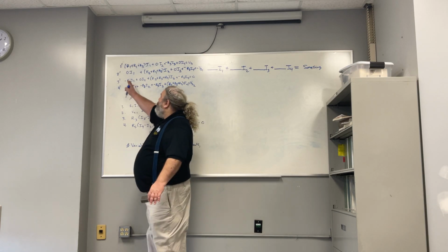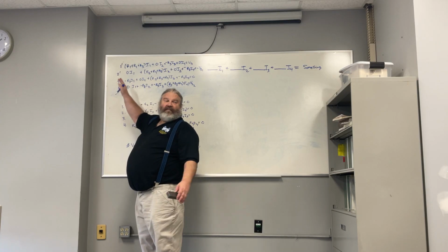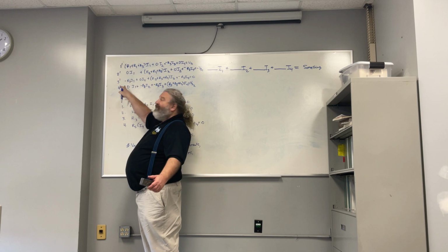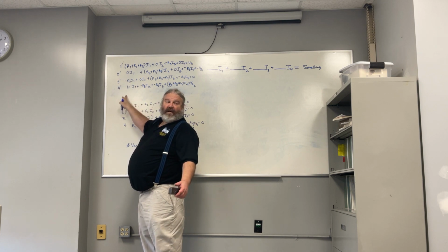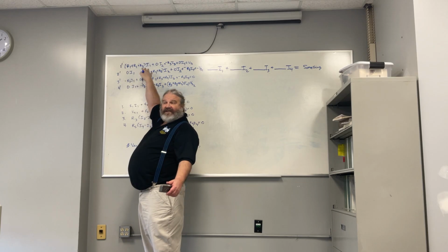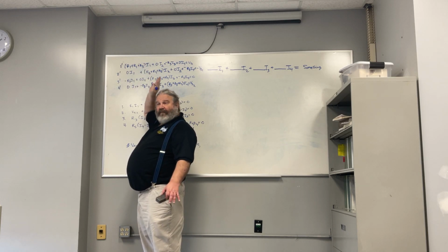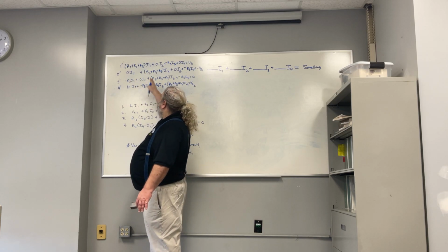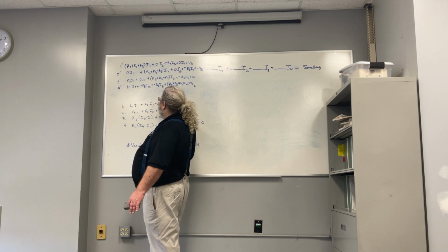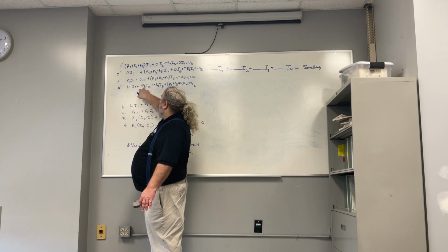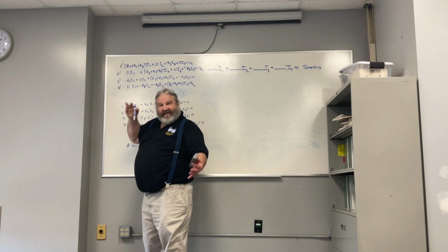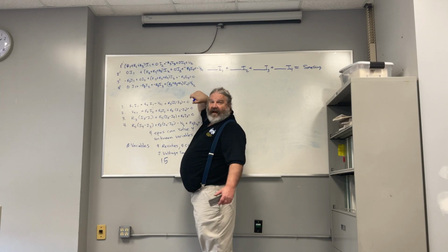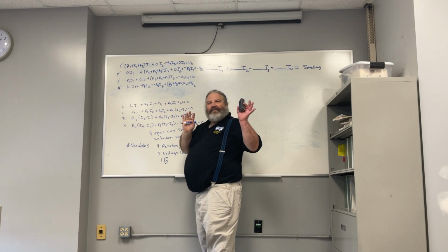And if you line them up, all the I1s, I didn't have space, but if you line it up carefully, all the I1s, you could just draw a line through the I1s. That's coefficient, coefficient, coefficient, coefficient. That's one column. So each row is an equation, each column is a variable. Everybody got that? Yes? I2, I can put a line through the I2s. It's 0, this, this, this. Everybody see that? Make sense? What's my B going to be? This, this, this, this. Got it? So it's bookkeeping. Just be careful and do it.